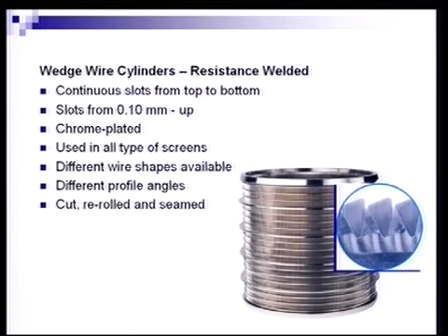Then they're cut off of the mandrel, flattened and re-rolled in an opposite direction. All those stresses are put on the basket, and all that stress ends up as a residual stress in the structure itself, so that under load these can be subject to failure. But a very, very good method by which we can get a higher open area for the same circumference and length of a screen basket.